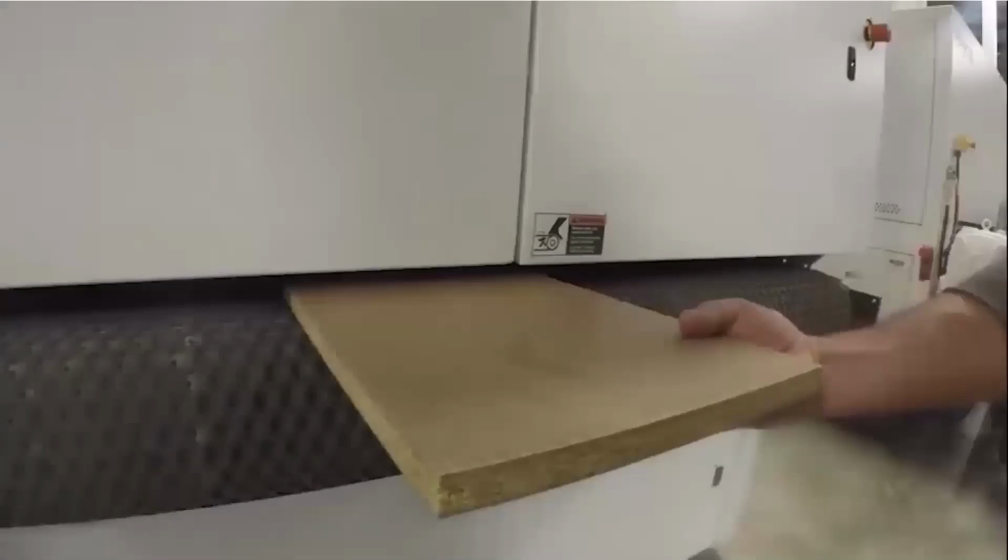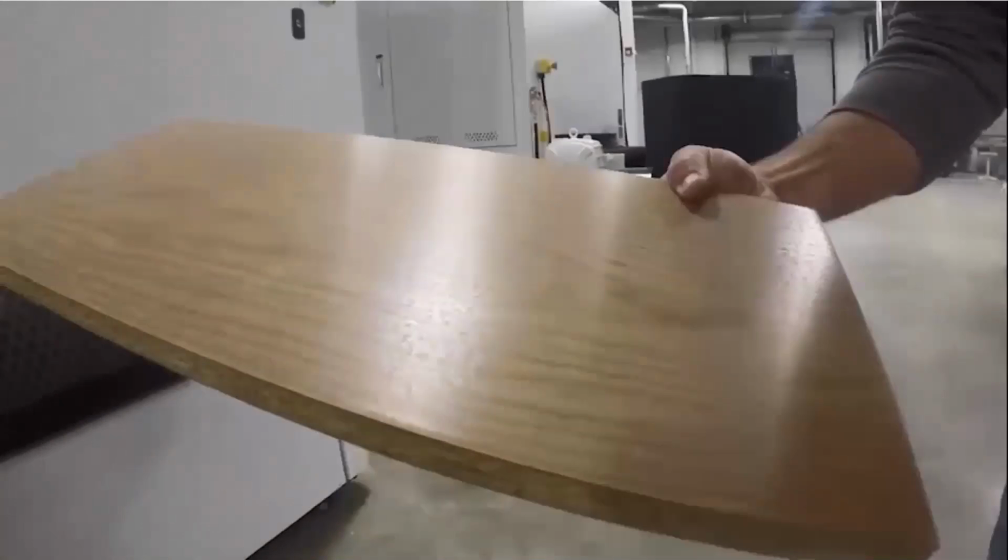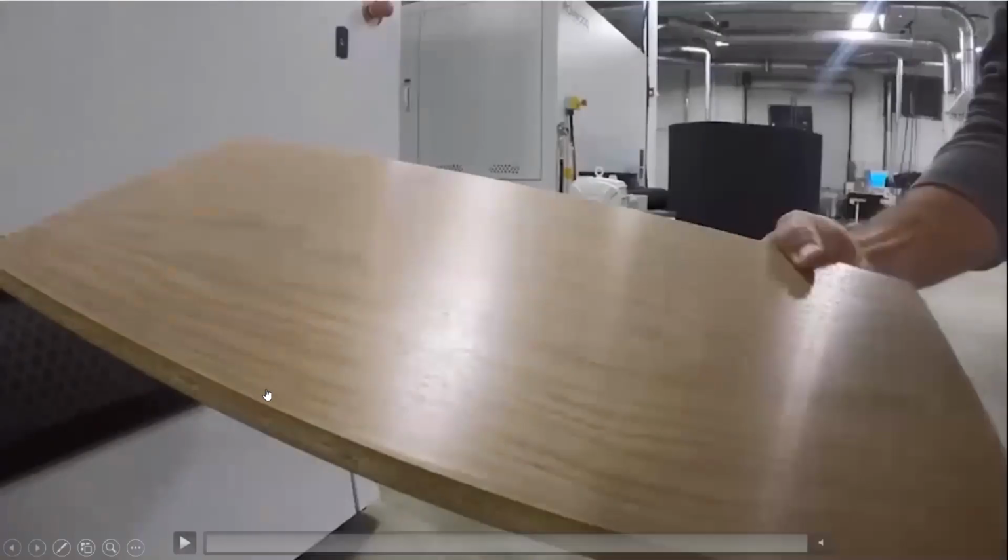The chevron belt's gonna sand the workpiece, and then we're gonna blow off the workpiece so that it's clean. And it comes out of the machine, and basically it's ready to go straight back to get its top coat. Now you can see, it's hard to see, obviously, such a finish in a video, but you can see some little dots here and there. And what that is we're cutting down those fibers that have raised up, and we're just overall smoothing out the surface and creating some mechanical adhesion. So it does a phenomenal job to create a very, very good finish downstream without a lot of labor involved.